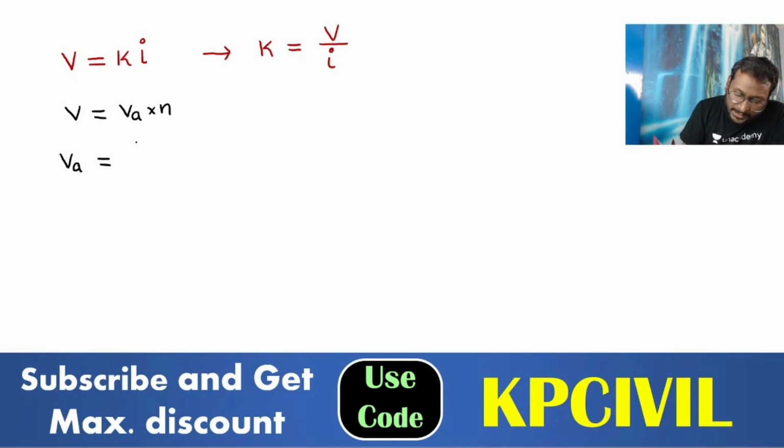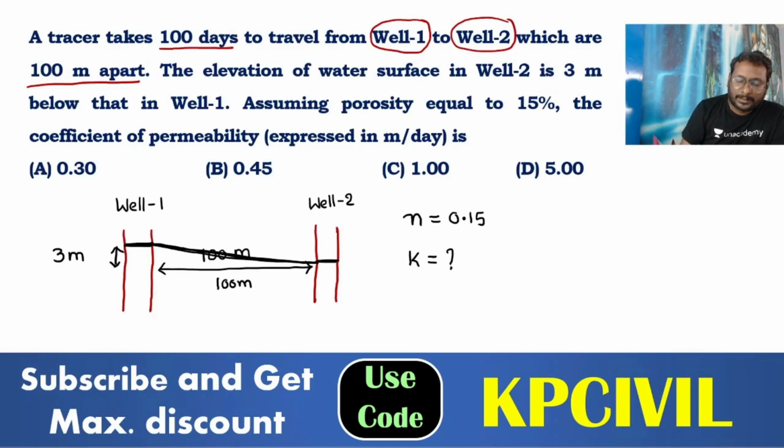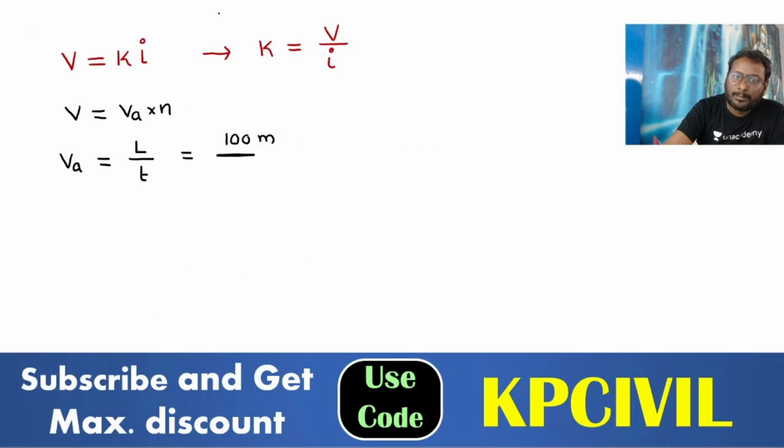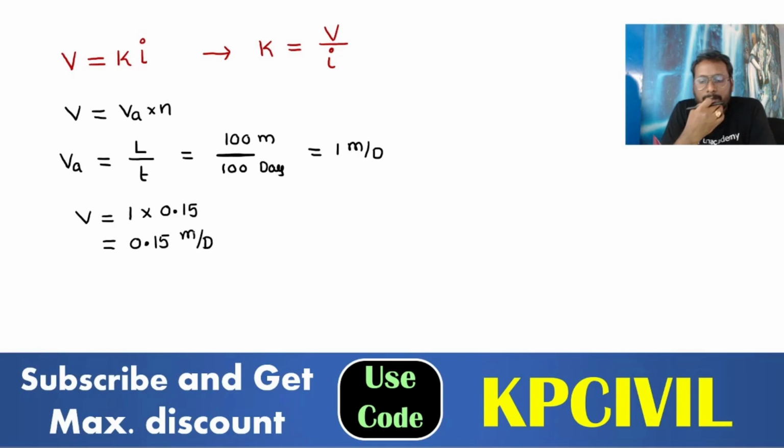VA is equal to distance by time, length of travel by time taken. 100 meters is the length of travel, and the time taken to complete is 100 days. So we'll take VA is equal to 1 meter per day. V is equal to 1 into porosity 0.15, so V is equal to 0.15 meter per day.